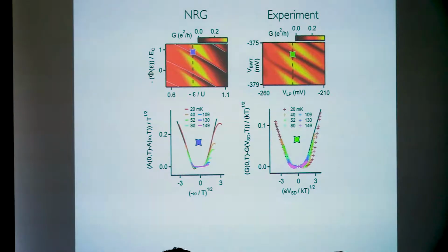The reason for that is that in an experimental system, you don't actually have independent axes. As I change the gate voltage on the small dot, I might also be gating the large dot at the same time. And so you kind of have to calibrate out those capacitances, or do the reverse and have your theorist try and match your experimental data by distorting the data suitably. But that can be done based on measurements of the capacitances.